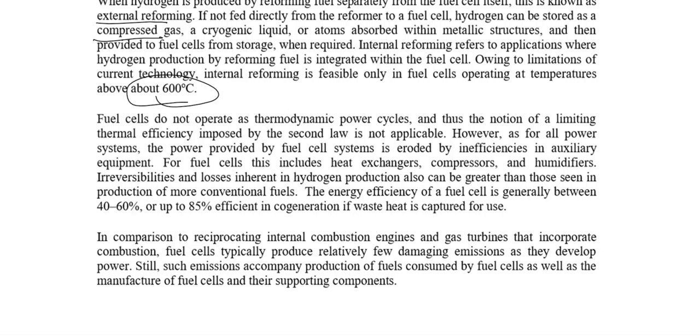So the efficiency of the fuel cell can go up to 40 to 60%, or even 85% if you are looking at cogeneration as well in SOFC. So it is more likely that you can get a good efficient fuel cell of more than 60% as well, and normally common fuel cells are 40 to 60%.